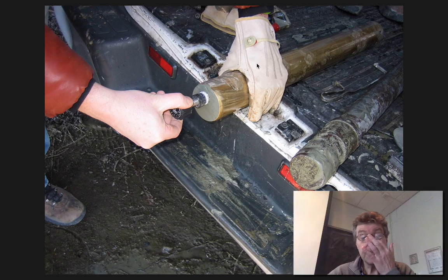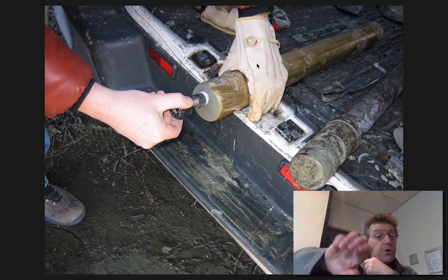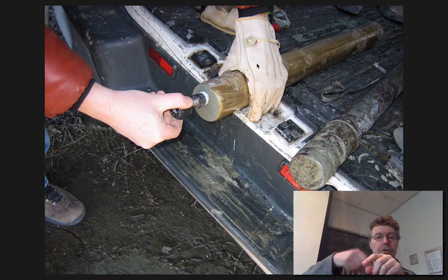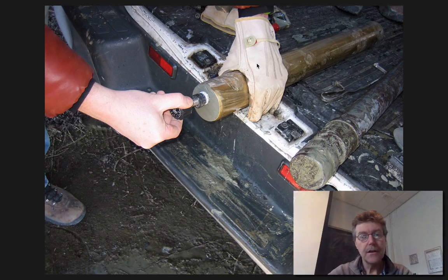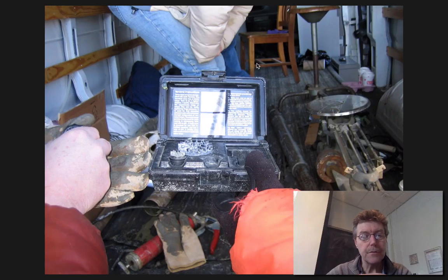Often one way of classifying these materials is how strong they are. So stiff clays versus soft clays would be related to how strong they are. And so this is something called a torvane, which is just a little torque wrench. So it's a little circle, the same size as a quarter, that has little protrusions coming out of it. You stick it into the end of the core, you twist it, and it registers the torque that it takes to shear it off, and you can use that to classify the strength of the material, stiff clay or soft clay, which might be useful.